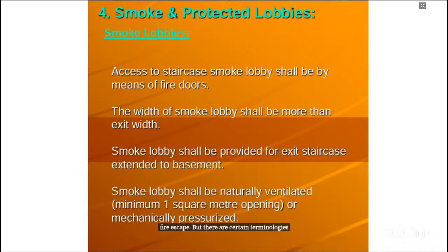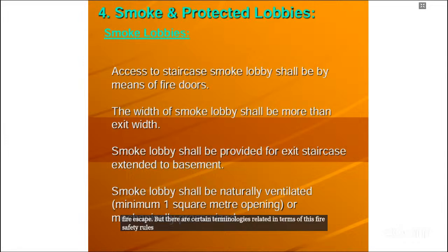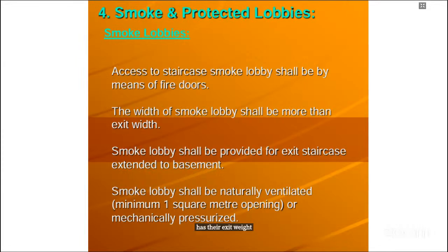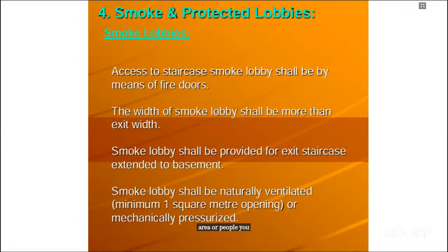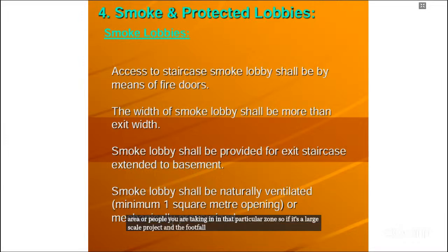related to fire safety rules, and that's what we are studying today, that we need to have these lobbies, and these smoke lobbies have an exit width more than that of the corridor which they are forming into, right? Smoke lobby shall be naturally ventilated, minimum 1 square meter opening, or mechanically pressurized also, depending upon your designer, depending upon the architect, and how much accommodated area or people you are taking in that particular zone. So if it's a large scale project and the footfall is high, you need to understand according to that, and the lobby has to be maintained according to that area.